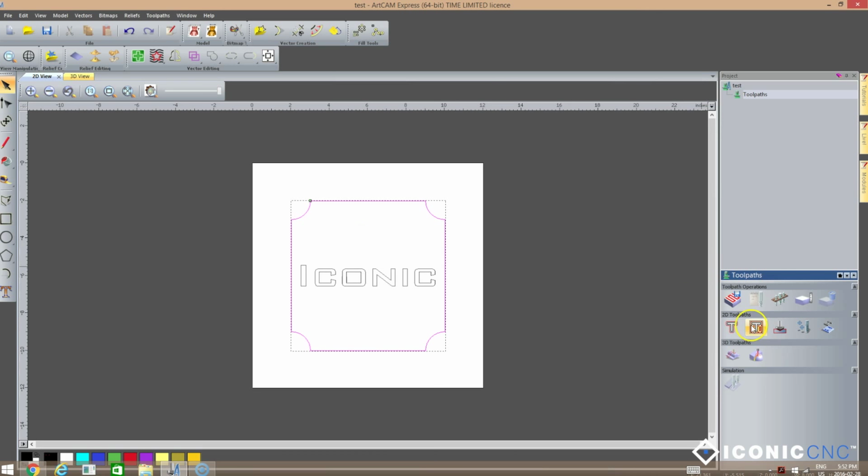The second toolpath option that you see here is called an area clearance toolpath. So let's suppose that I wanted to clear out an area in the middle of this, not take it all away, but maybe just create a pocket, if you will. So maybe I want to machine an 1/8 inch or a 1/4 inch depth pocket out of the center of this project. Now I'm going to use an area clearance toolpath. So it's going to basically hog out all the material in the center here and machine it right to the outer edges. And that is an area clearance toolpath.